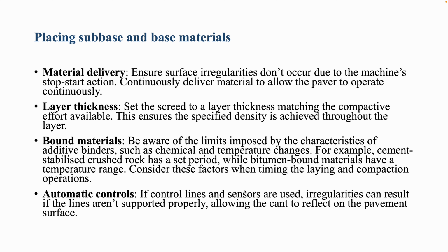During the placing of the sub-base and base material, we have to be wary about how the material is being delivered and the compaction of different layer thickness. And if there's a bound material, we have to be aware of the limits imposed by the characteristics of the binders, such as chemical and temperature changes. For example, cement stabilized crushed rock has a set period, while bitumen bound material has a temperature range. We have to consider